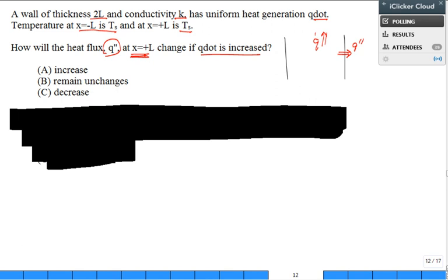All right, let's go ahead and stop. So this temperature profile is always symmetric, isn't it? If I asked whether Fourier's law is still applicable, is q double prime equal to minus k dT/dx, sure, it's still applicable.